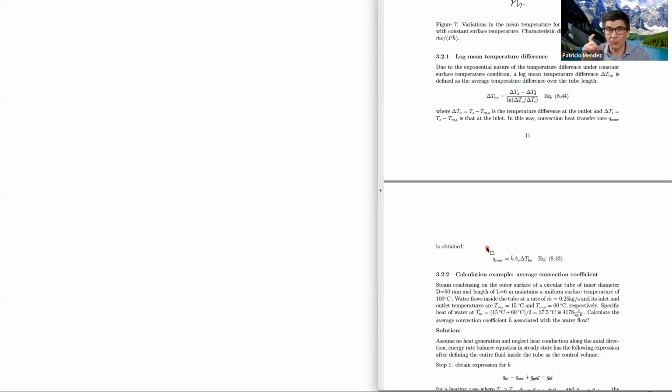So this is a really, really smart thing that is used very much for heat exchangers. And it all has its roots in these internal flows. We didn't need to define delta T log mean before, because a fluid in external flows doesn't change temperature.